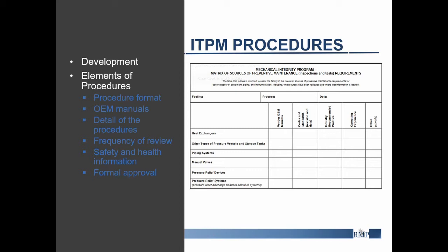We also get questions on how often, if any, should the maintenance procedures be reviewed and updated, and should they be certified periodically like SOPs. Formal certification on the annual basis is generally not warranted for maintenance procedures. However, some sort of periodic review and update is prudent, as the CAPP program actually requires that this be updated as PSI is updated in order to change the maintenance of equipment. So there needs to be some kind of system in place in order to monitor the PSI and trigger a change to the mechanical integrity program. More on that will be included in some of our other webinars.